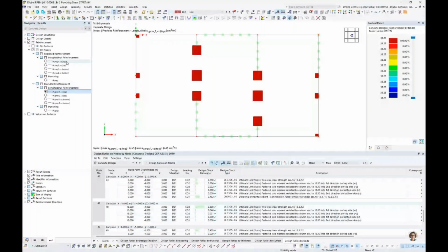If it's not, then we would want to go back into the surface element directly and maybe specify additional longitudinal reinforcement only at these locations where we're carrying out punching shear. But I thought that was worthwhile just to mention here that that's also important.